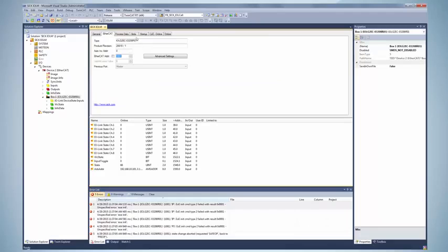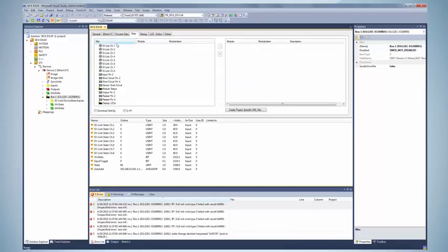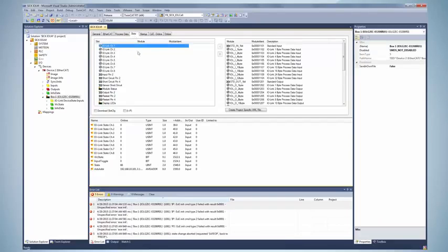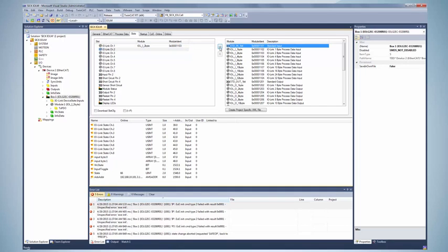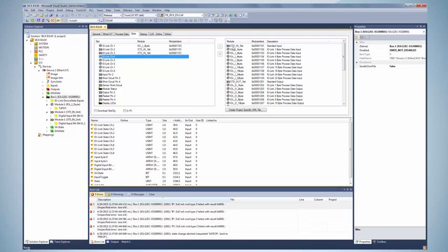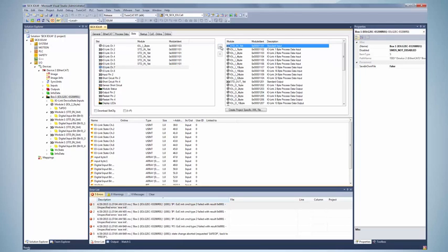For configuration of the I/O link master ports, the tab Slots needs to be open. In this tab, it is possible to configure each I/O link channel. In this example, an I/O link device with a process data length of 2 bytes is connected to channel 1. All other channels, even if these are not used, need to be defined as well. Select a standard input module if no I/O link sensor is used. Additional slots can be defined here as well. In this example, this is not needed.